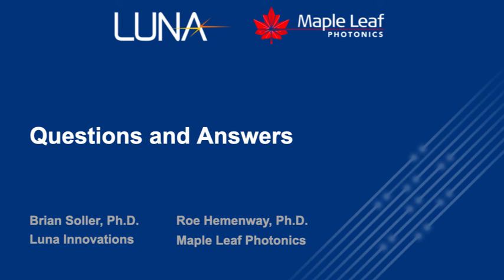That's a great question. So our system establishes a coordinate transformation between the chip surface or the wafer surface and the coordinate system used by the optical probe station. And that takes a few minutes, typically 5 or 10 minutes to set up at the beginning of a test run. And then once you have that and it's established what X, Y, and Z is and planarity, then it becomes a very simple task for the system to scan over and pick up and log the location of all the grating couplers or edge couplers in the chip.